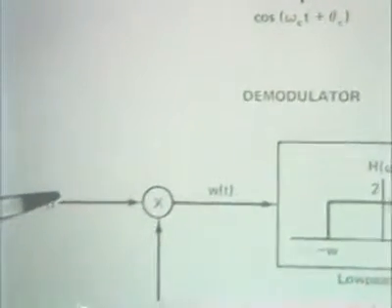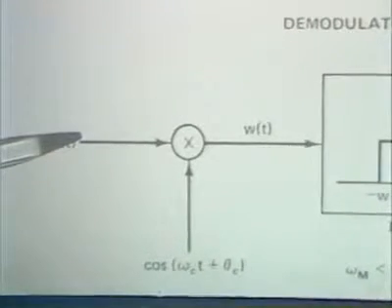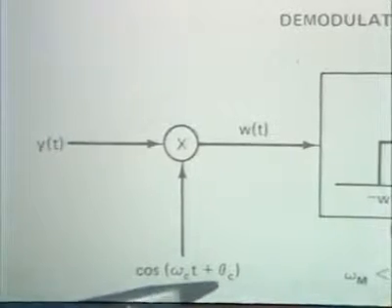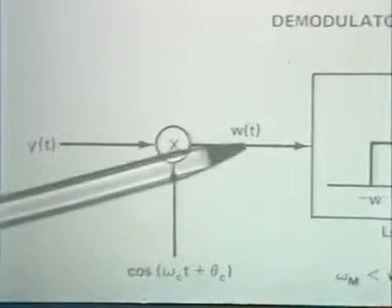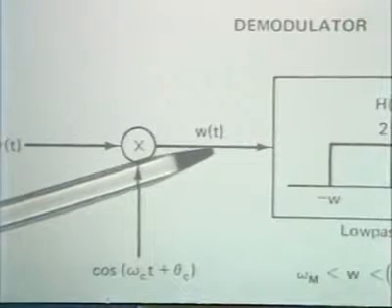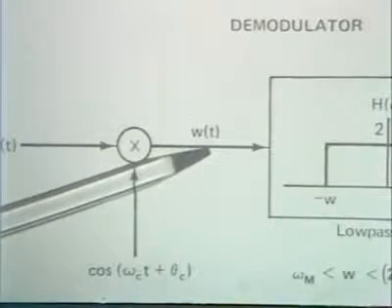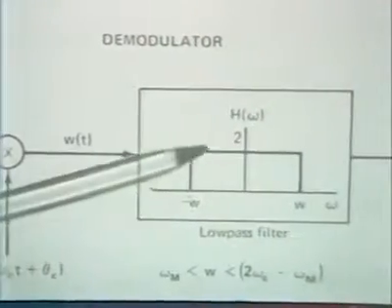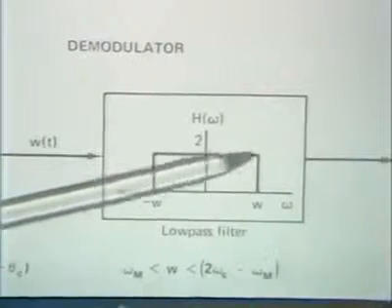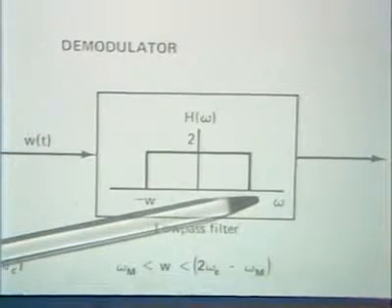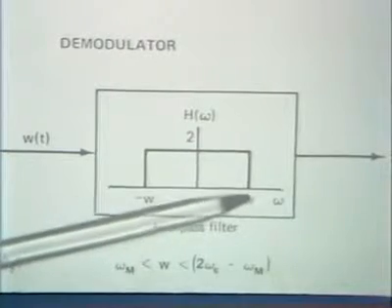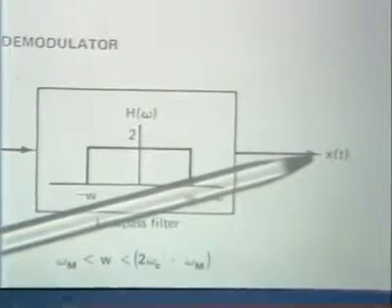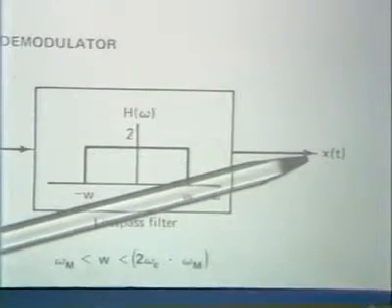we would take the modulated signal, modulate it again with the same carrier signal, and as we'll see later, it's important to keep the same phase relationship. This result is now not yet quite the demodulated signal. We need to process that with a low-pass filter that extracts the part of the spectrum around DC and throws away the upper part of the spectrum that gets generated in the second modulation process, and the resulting output is the original signal x of t.